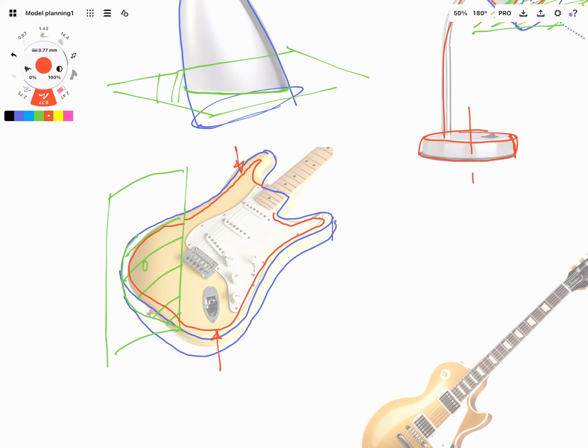You'd extrude it, which is the first thing. Second thing is you figure out the next largest feature on the body, and then third is the fillet around the outside. So that's something you've got to identify as I break things down in my head into primary, secondary, sort of tertiary steps. So when you see your object, go, okay, what does that look like without smaller details on it? What does it look like without the fillets?